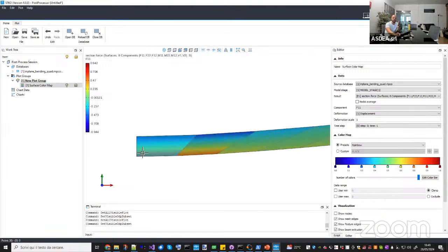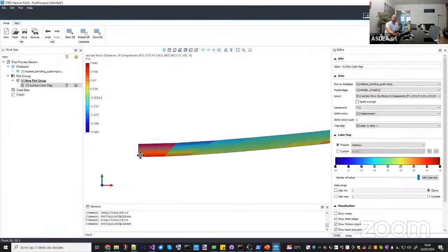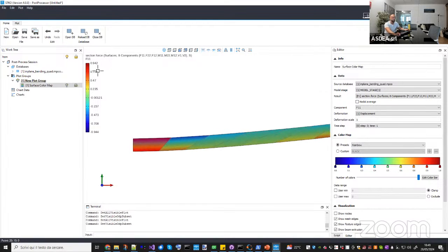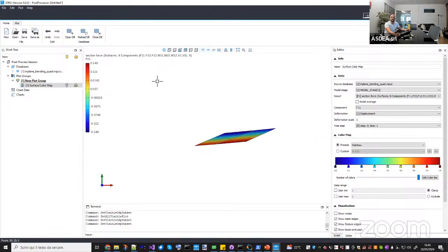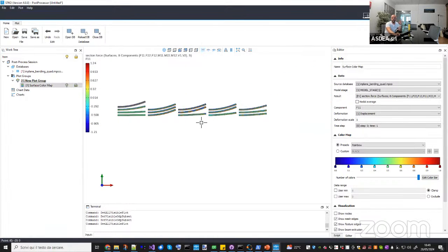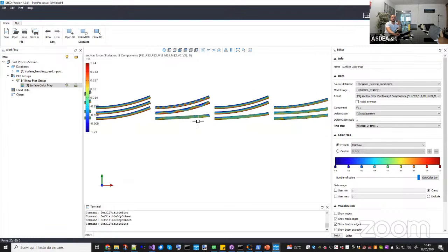As you can see here, for example, this element has only one side that is distorted, the other one is right. And the stress solution here is pretty good. But if you go in the middle, it becomes super stiff. So instead of 1, it becomes 0.15, okay? So the idea is try to avoid this one.